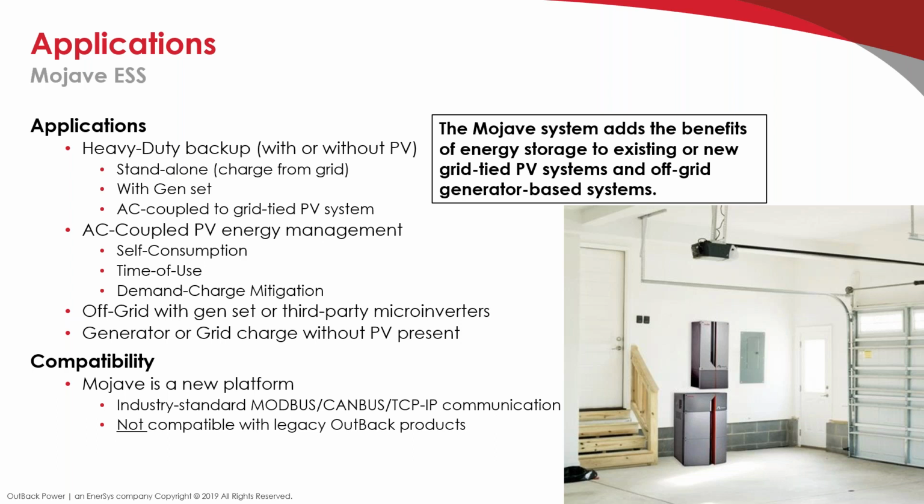We've got self-consumption, obviously. If you want to limit your export, there's a caveat on AC coupled: if you're going to limit the export from the grid tie inverter, once the battery is full, there's not a lot we can do about that. So you'll have to have some device on that grid tie inverter that limits export if you're in that situation.